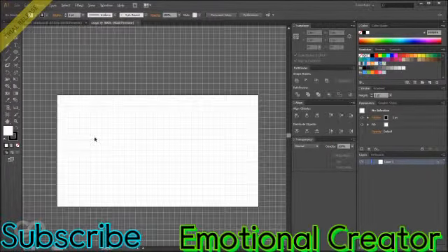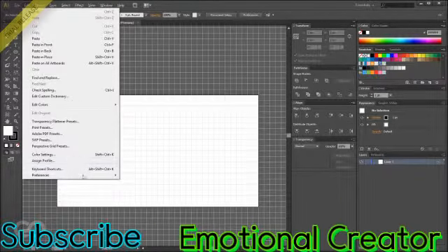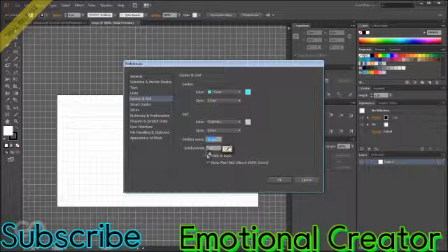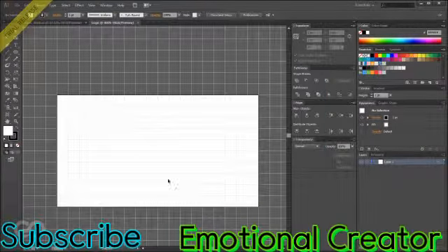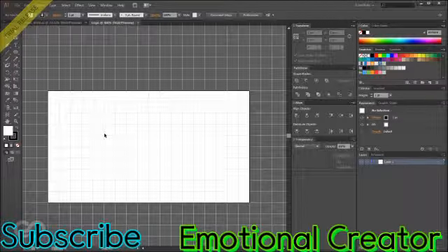And this is basically what I want, but you can see that it has subgrid lines which I don't really need. So let me go ahead and get rid of that. The subdivisions, I'll just set it to 1. Okay, done. So this is basically I have 10 units going across on the top to bottom, and I have 18 units going across. So this is the first step.